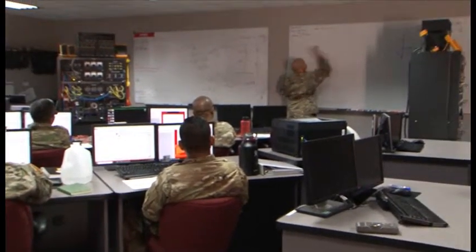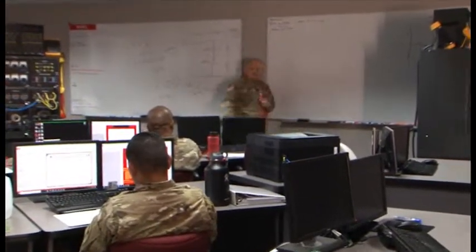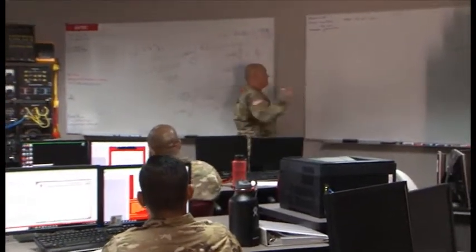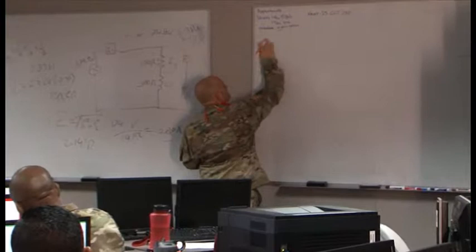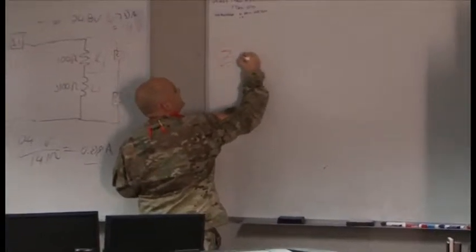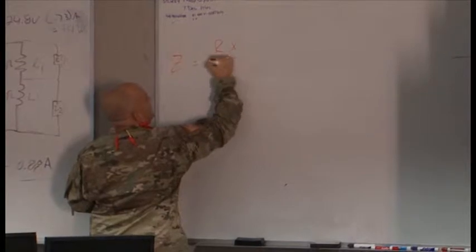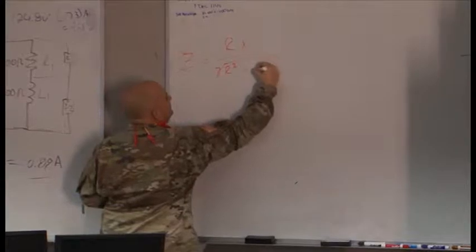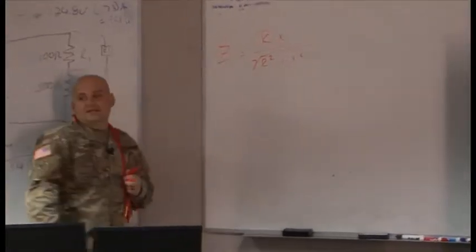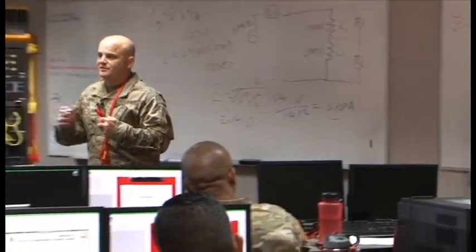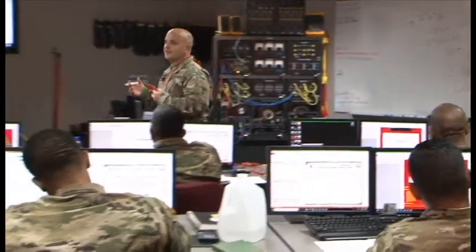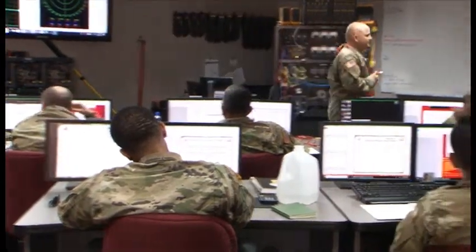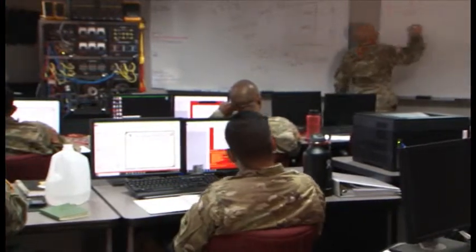In a parallel circuit, a parallel RC, RL, or RLC circuit, and you want to find the impedance, just like we did over there, 1 over Z, oh, no, I'm telling you the other one, hold on, Z equals R X over the square root of R squared plus X squared. Now again, that X is going to be whatever the delta is between the capacitive and the inductive reactance. Okay, so when you see the X in there, you're just talking about a delta. All right. Now this is how we're going to calculate that.